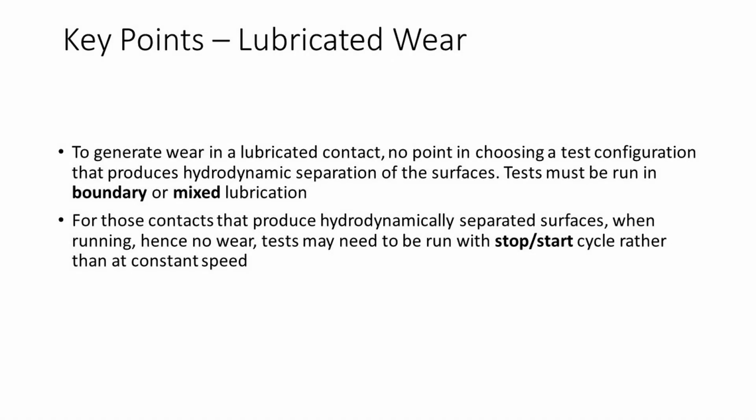To generate wear in a lubricated contact, there is no point in choosing a test configuration that produces hydrodynamic separation of the surfaces. Tests must be run under boundary or mixed lubrication. We need to consider the following questions.